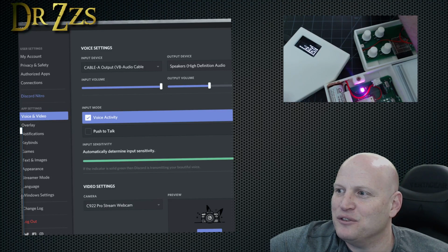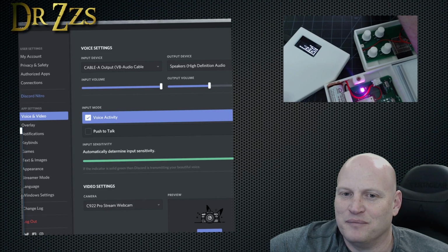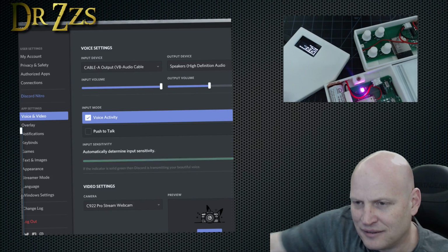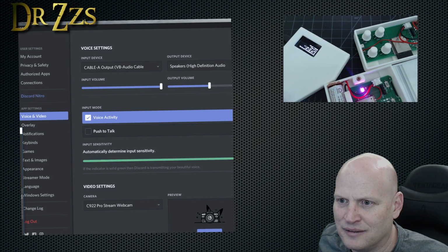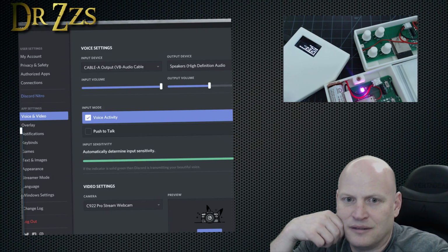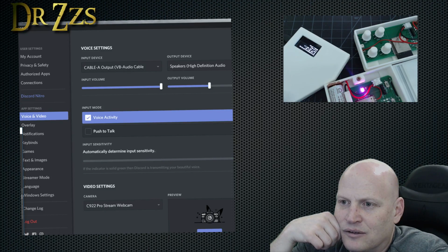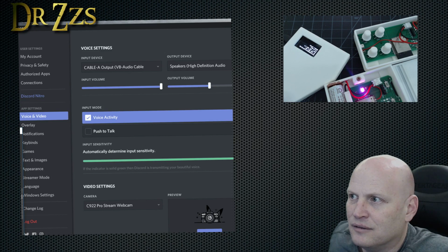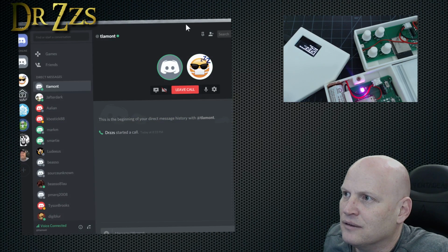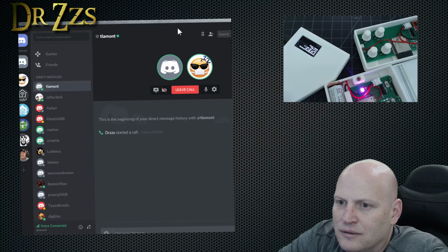All right. Tony, would you explain to us how you decided to start using ESP-NOW and the ESP32? Tell us about the great advantages and all. Basically, the ESP-NOW protocol is still part of the Wi-Fi protocol. It doesn't connect to your network. It just sends, as Rob says, a broadcast packet out. The receiver listens to and responds to it. That's why only Espressif chips can be used.